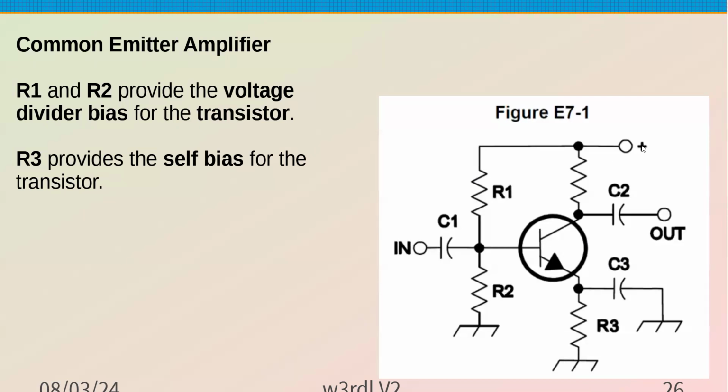No, this plus is your power supply. N is where your signal is. It's DC isolated from this bias network. So you don't see that voltage back there on the input. So only the AC part of that signal comes through. And if everything works right, it amplifies it.